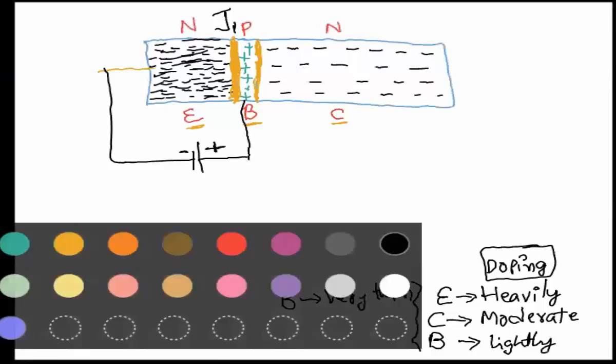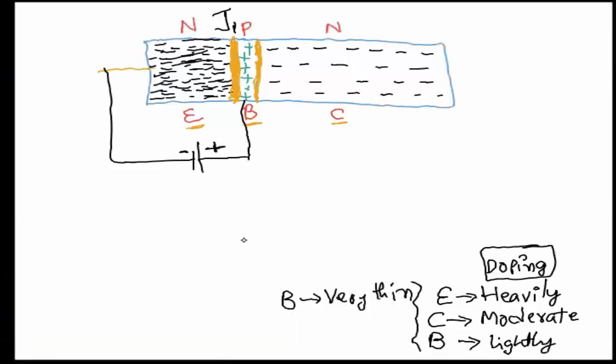then definitely some current conduction will be happening, meaning that this side is negative. So from the source, negative electrons will be entering this side, correct? Which will repel the electrons that are already in the N region. So all these electrons will carry over the barrier because you are forward biasing the junction.